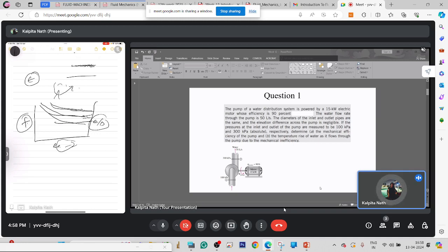At very high Reynolds number, the friction factor tends to become independent of Reynolds number. This independence starts more quickly for rougher pipe. The viscous sublayer present in the turbulent layer, the layer very close to the surface, becomes thinner and thinner as one approaches high Reynolds number.